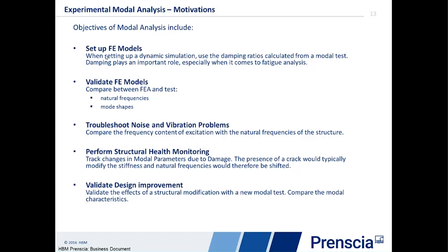Coming from some test can only be better than leaving the default values. We're currently writing a paper for SAE 2017 where we'll show how important it is to set this property properly. Just as we said, if there's a high magnification factor, then the stress response will be magnified, and therefore the fatigue damage will be exponentially impacted. So it's very important.